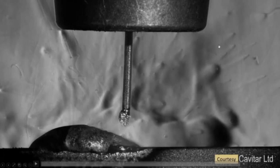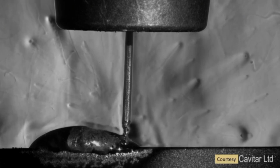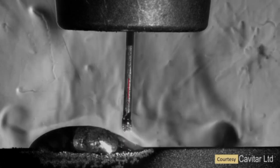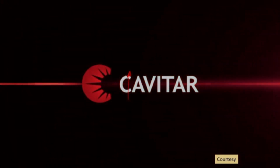This is a typical video of how the CMT works. The slow motion of the CMT process can be seen from this video. Here we can see when the short circuit happens, the wire is going back. So it is pulled back by a mechanism, and as a result it leaves the droplet behind. So this is how CMT works.